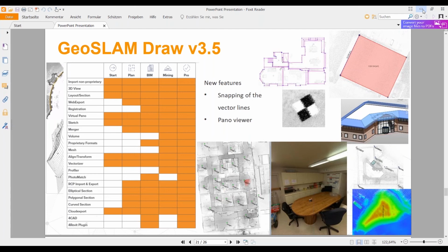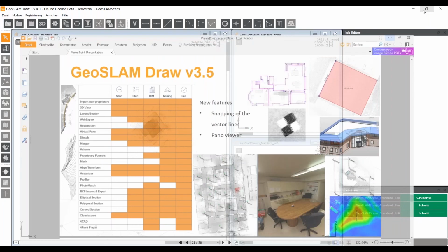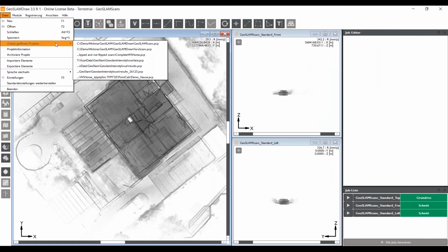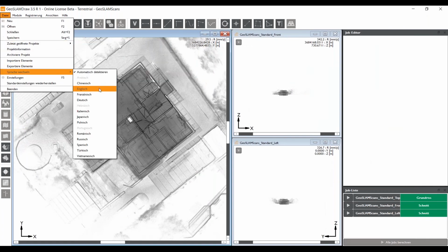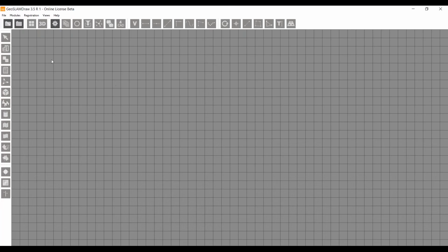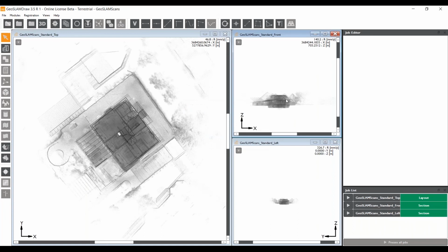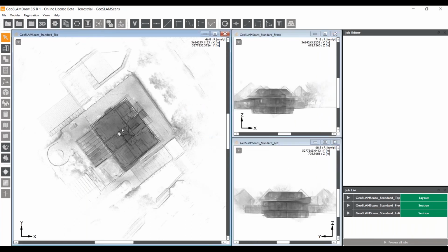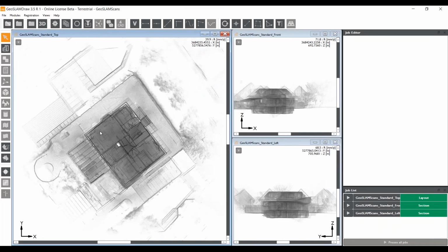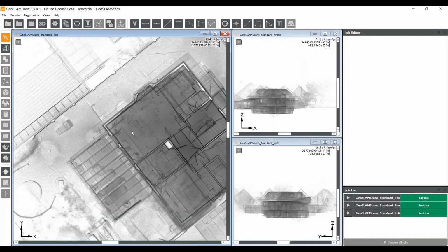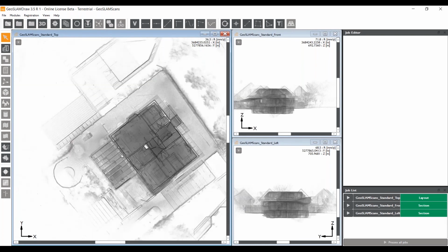All right, so it has processed. I wanted to switch the language to English. Yes. All right. So now here we have our data, and we want to combine that with Faro data. So this point cloud here is already transformed. You see here the coordinates. It's in world coordinates, since we used ZEB Locate with the GPS antenna and walked outside.